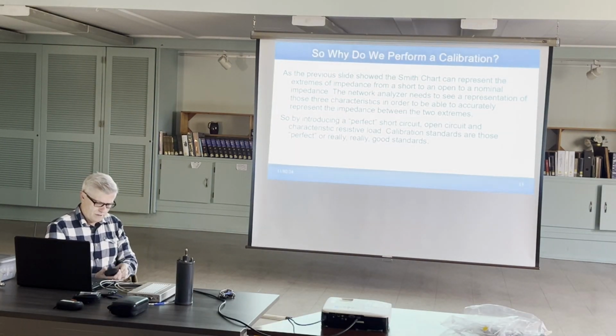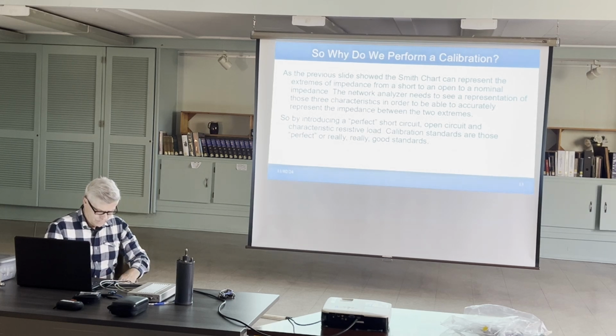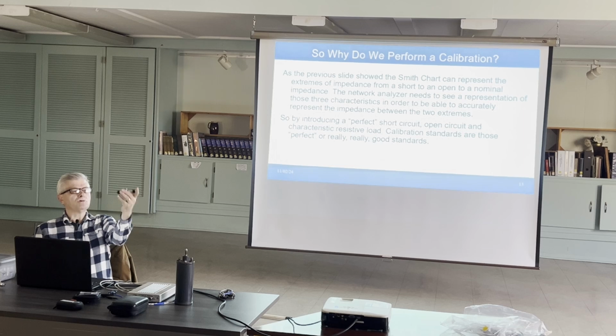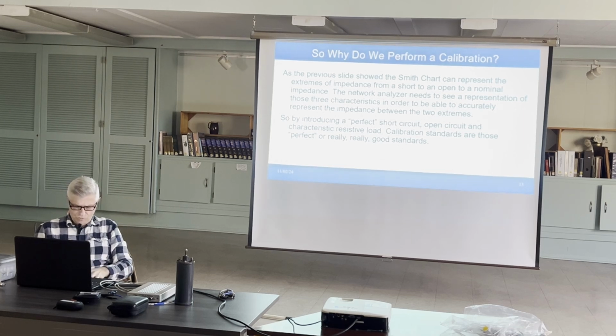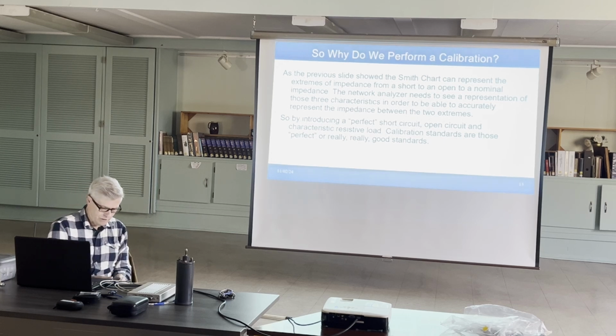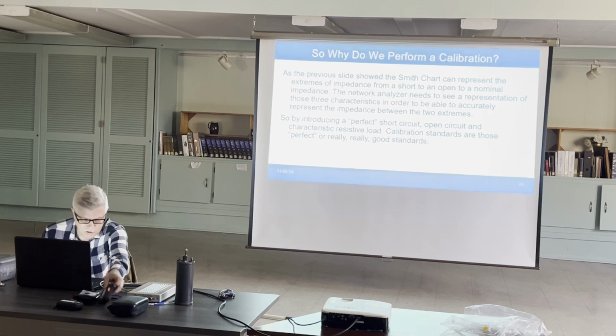and I have a couple of different N type. This was already open. This is an N female standard, and the other one is an N male standard. There's also a barrel in here for your through measurement. Now I'm going to go through and do a calibration here. Now we're getting into the show and tell, which is the interesting stuff.